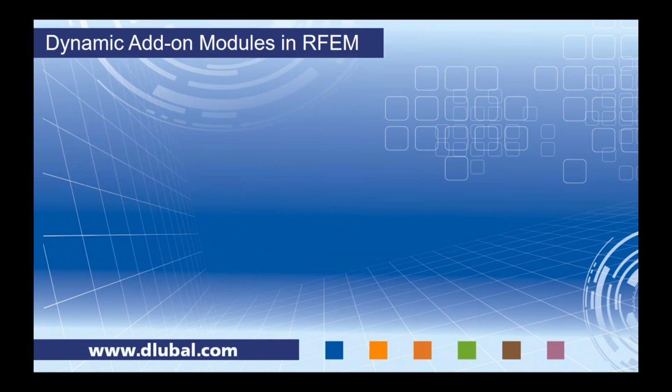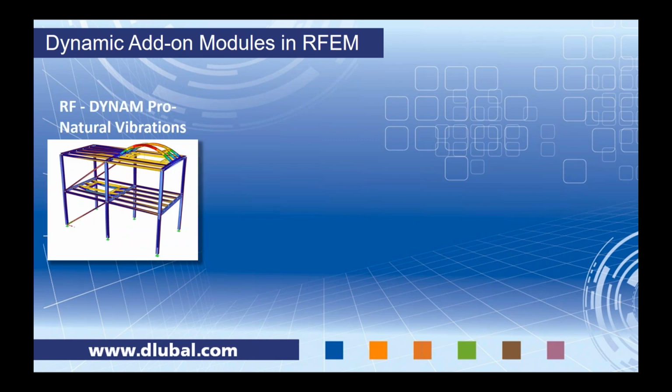So regarding the dynamic add-on modules in RFEM, RFEM is our main program. This is where we're going to fully model the structure. We can load it with some various static loading and run an analysis. But anything to do with dynamics, whether that's a natural vibration, forced vibrations, or seismic analysis, does require one of our dynamic add-on modules. So the first is RF-DYNAM Pro Natural Vibrations. This is going to run an eigenvalue analysis that allows us to find the natural frequencies and mode shapes of our structure.